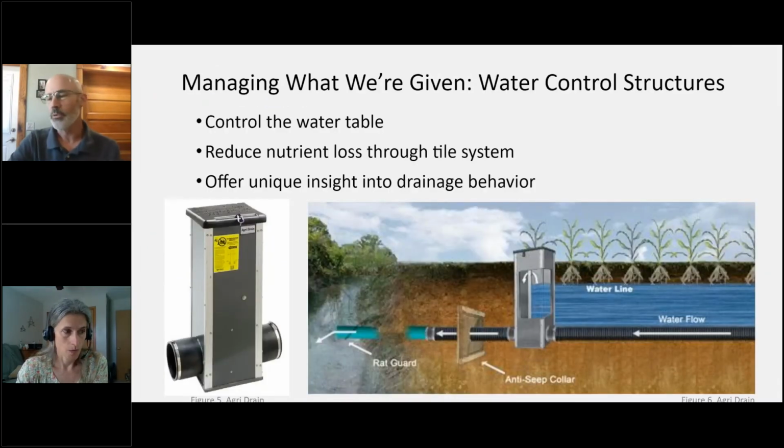Well, what we want to do is be able to use all the moisture that does fall into a field. How do we keep it for the crop? This farm also does have these water control structures. There are 4 of them along the edge of a field. The tile on this farm is anywhere from 25 to 33 feet apart. It was an older system from the 80s that we added lines into, but we have these water control structures to be able to keep the subsoil moisture there as long as we can. They still are holding some moisture there.